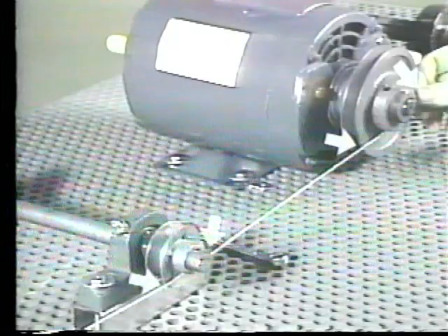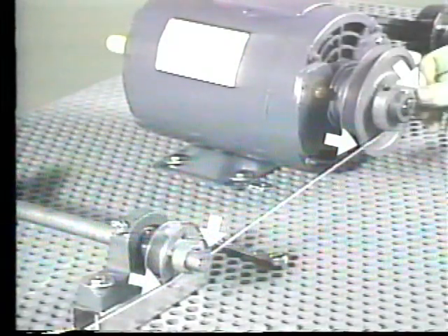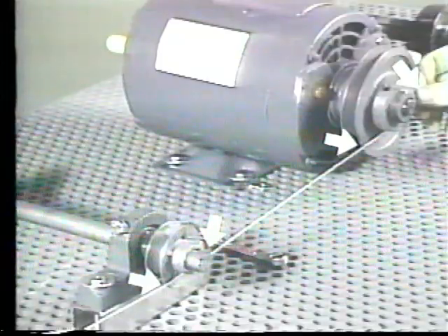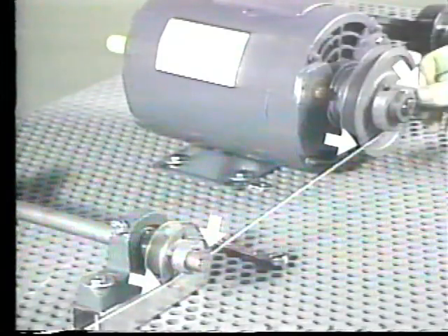The string or the straight edge should touch 2 points on each sheave. When the driver and driven units are far apart, better results may be obtained with a string because any deflection is easily seen by sighting along the length of the string after it is in place between the sheaves. Long, accurate straight edges are sometimes difficult to locate.